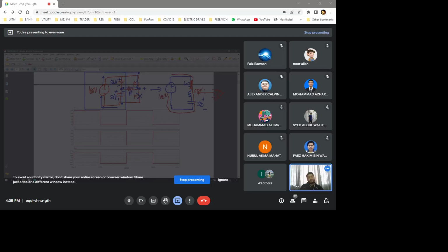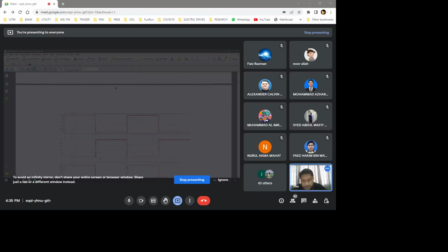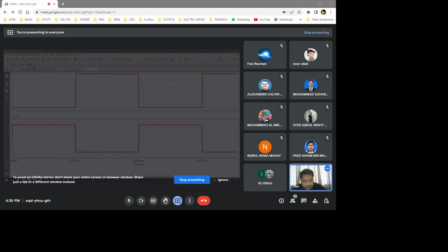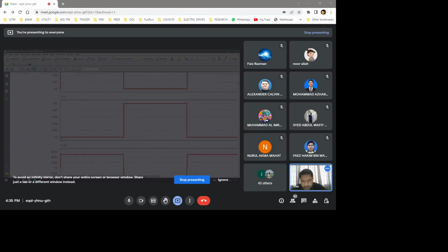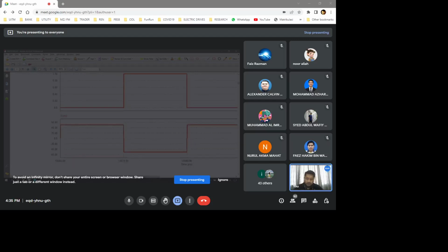Voltage drop across that. So if you look closely at the output now, remember we have the 100 volt at the input. So V load now becomes 50 volt there, 50 volt across that. And whenever the bottom switch is on, then we have a minus 50 volt. You can try that. So if you look at the output, this is a square waveform, isn't it?